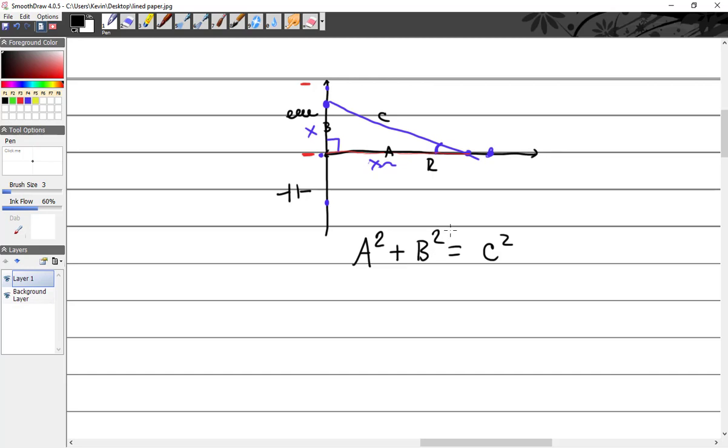Well, just for an example, and it doesn't work like this in electricity, but let's just say we had a triangle. And I said this is, and drawing's not to scale, 7 inches and 9 inches. What is my hypotenuse? And you will be doing something just like this. I will be saying something like you have 9 ohms and inductive reactance is 7. What is my impedance?